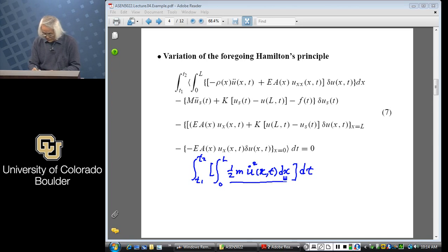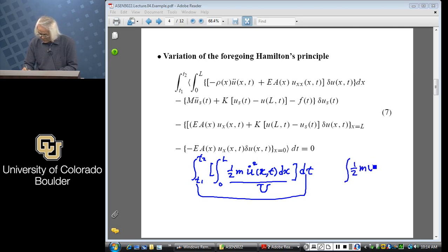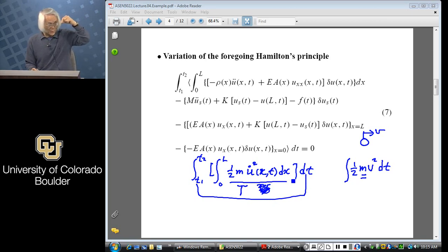So this part is finding out the strain energy. That part is coming from Hamilton's principle, time-definite integral. Remember for the discrete case, we did a similar thing. In this case, we are only using lumped mass and velocity at that point. Okay? In a continuum case, what we have to do, this is not true. This is T, I'm sorry. We get the total kinetic energy for each of those infinitesimally small segments of space, and then we do the time-definite integral. Okay? All right.